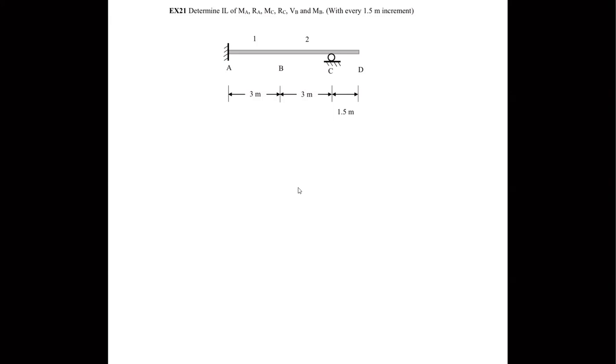Okay. Now, because I said that we will only limit the influence line of the indeterminate structure to 1 degree of redundancy, this problem should cover another remaining possible case. This is a 1 degree of redundancy prop cantilever. Okay. And again, when I see something like this, I prefer to remove the reaction at C. So my primary structure will become something like this.